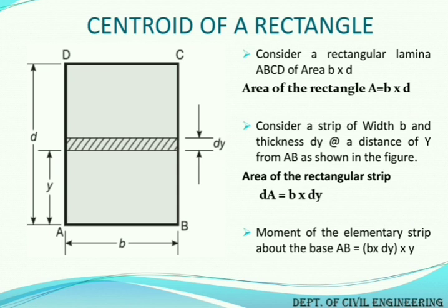So remember this: whatever is the axis under consideration, we will need to find the perpendicular distance as the centroidal distance. In this case AB we are taking as a reference axis, about which all the moments need to be calculated. Hence, our derivation will end when we obtain y bar.